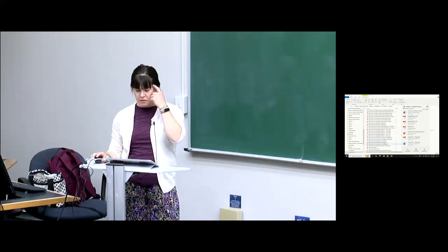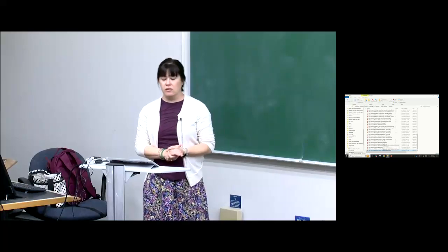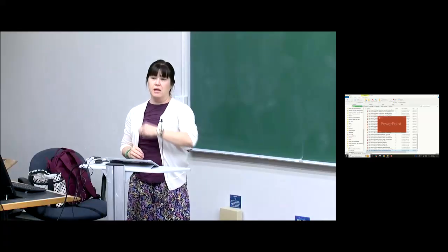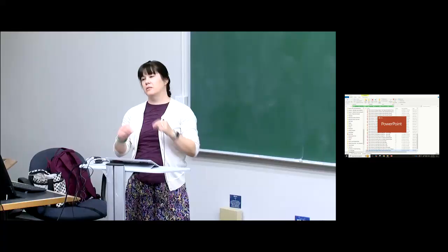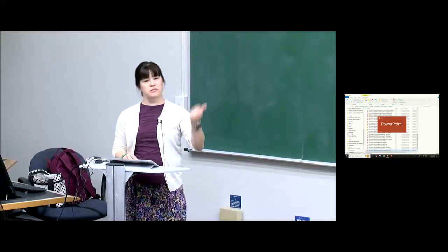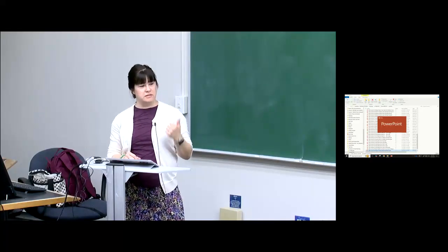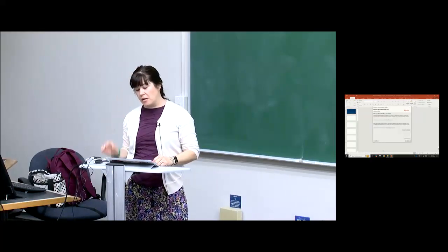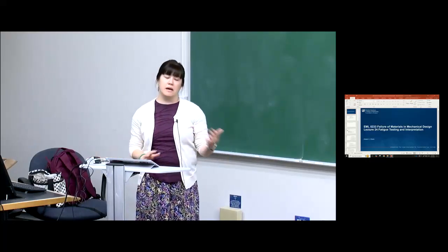Those spring clips, we had to analyze if they would fail due to fatigue. And so it took going all the way back, for those of you that solved every part of the problem, going back to mechanics of materials, right? How do we determine what the stresses are in a particular part of a compound beam component? And then what is the stress state, which we talked about at the beginning of the semester? What are the principal stresses? Does it fail due to static loading, right? We had some complicated examples, but the concepts of those things were things that you should already have a lot of experience with.